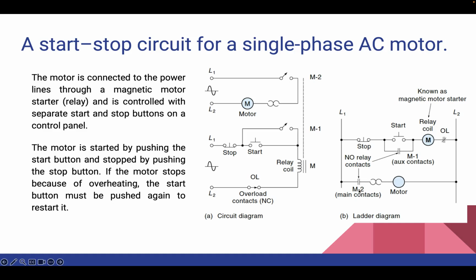So now, apart from a safety consideration, the sealing circuit is very beneficial for managing power restoration scenarios. Instead of all motors starting simultaneously after a power outage, causing a surge in the current, motors can be restarted individually, or they can be started in a group in an orderly manner.